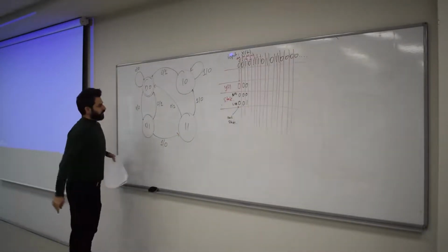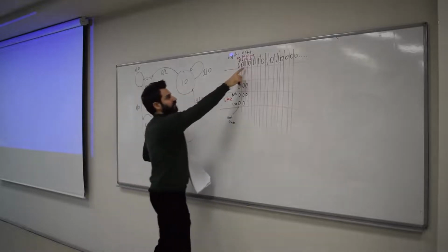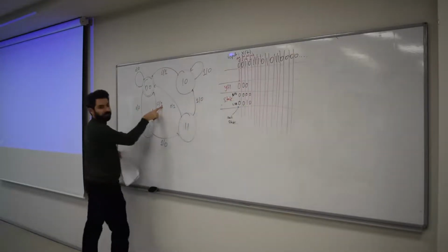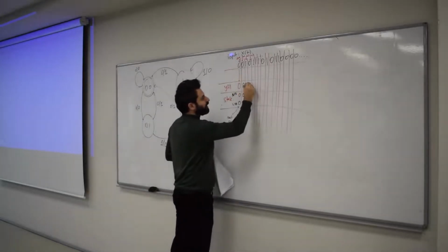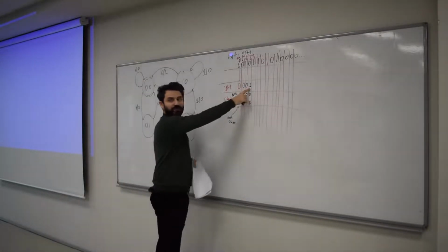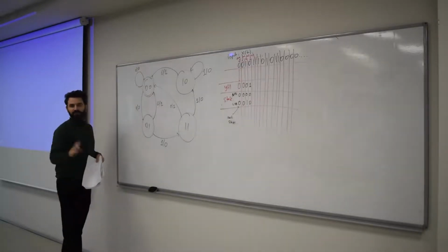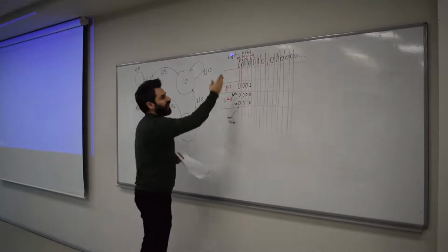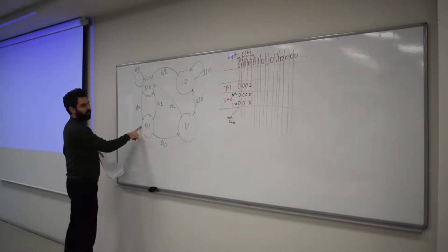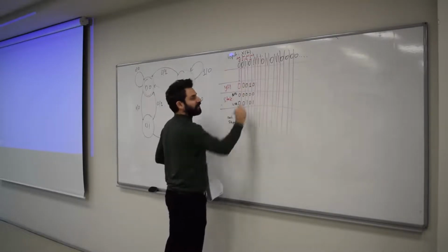So it's 0, 1. Okay, now then I see another 0, so that means I go back to where I started, because that is what this is saying. Okay, so therefore I'm going to go back to my initial state, but I push out a 1 here, you see? I push out a 1 here, so that actually creates a 1. Okay? Now you have to think about why this 1 has been created. Because of this one, right? Okay, let's keep that in mind and continue, and see if this observation changes as the input moves through time. So we are in the initial state now, and then I see another 1, and that makes me move from 0, 0 to 0, 1, and then I create another 0 output.